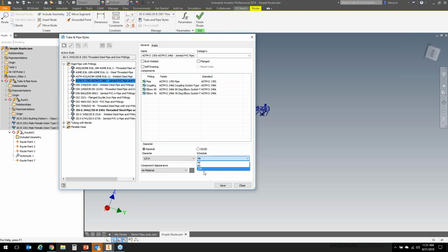Does it do support points and requirements for mechanical work? You can lay out points first if you want to, Steve. If you know your point locations, you can lay those out in your assembly, and then basically selecting your path, a manual path, selecting each one of those points. That would work. That's the old way of doing things, really. The way that tube and pipe used to work in the beginning required you to have axes and points along the way.